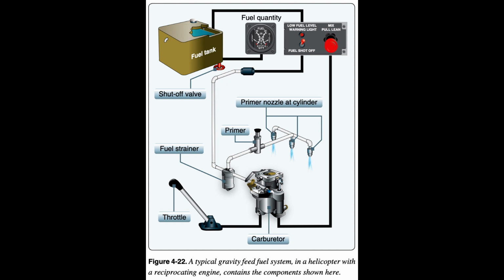Caution should be used to eliminate unnecessary or erratic maneuvering that could cause interruption of fuel flow to the engine. Although these systems must be calibrated, never assume the entire amount is available. Many pilots have not reached their destinations due to poor fuel planning or faulty fuel indications.